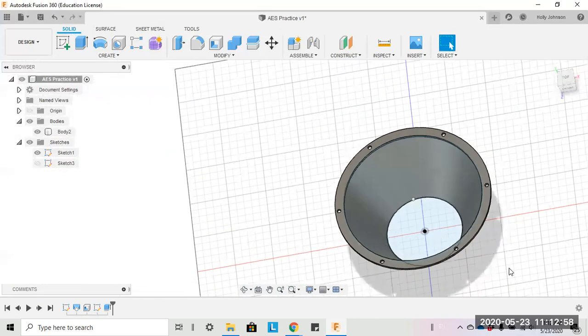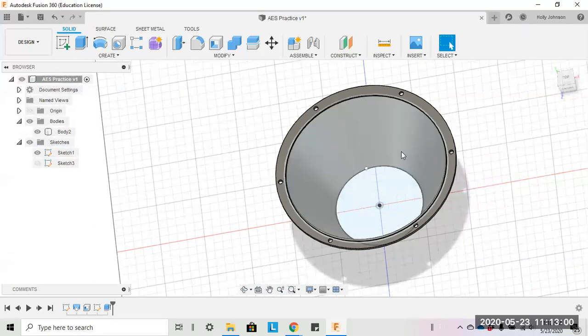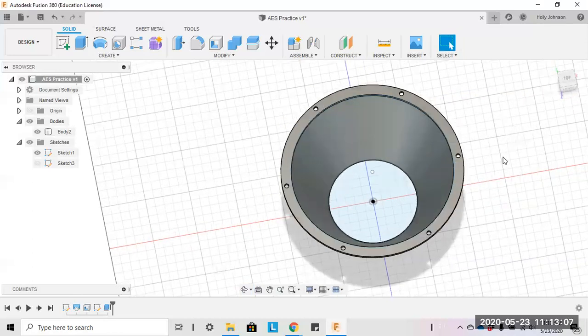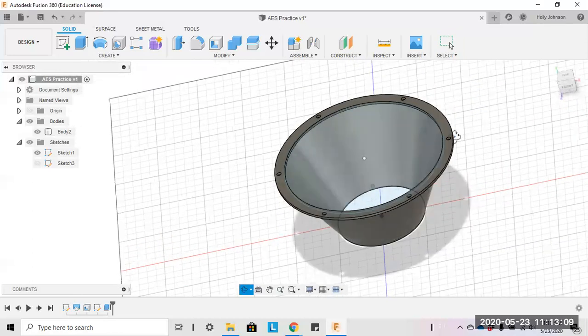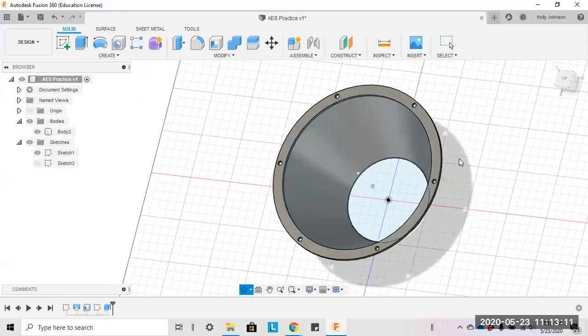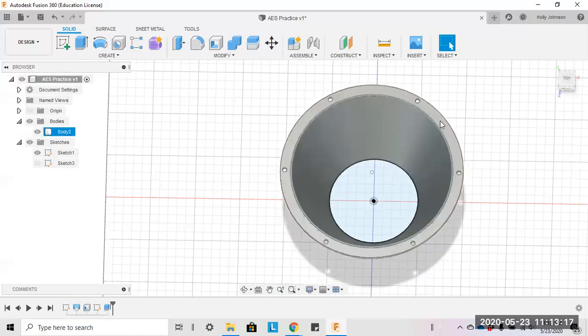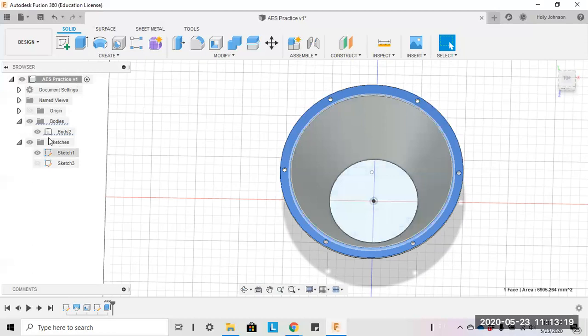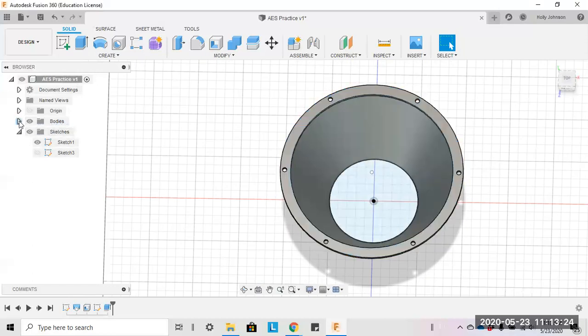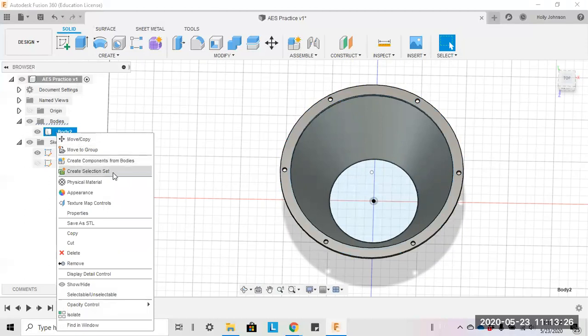Now, this comes in more if you're doing FEA and different types of analysis on this: you'll want to define the materials as well. Let's say I want a paper cone with a painted metal rim. You can go under bodies, I believe, and select the physical material.